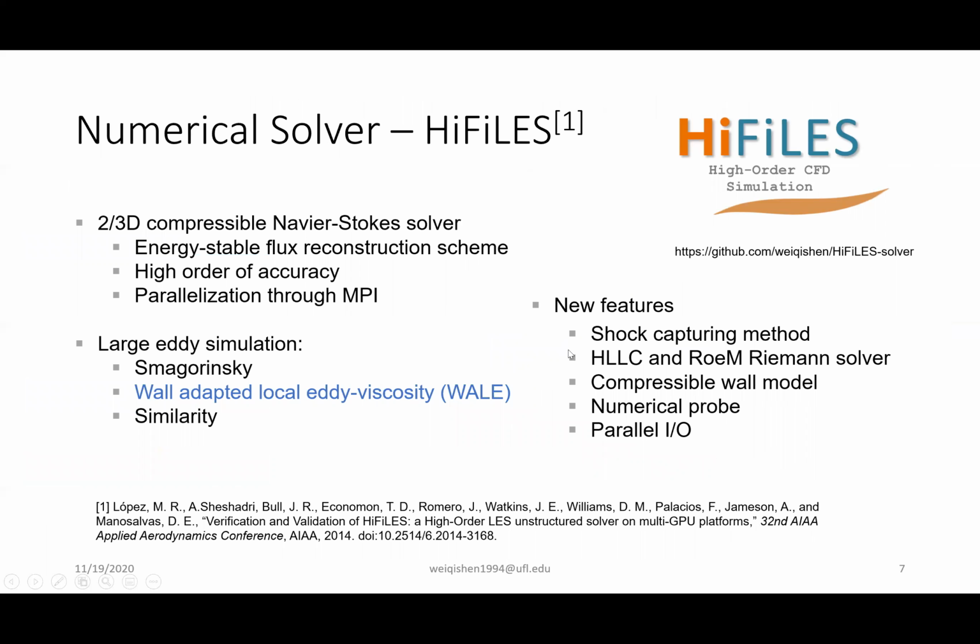The numerical code used in the present work is called HiFiLES, which was originally developed by Stanford University to demonstrate their newly developed scheme. The solver is a three-dimensional compressible Navier-Stokes solver, which is based on the energy-stable flux reconstruction scheme to achieve high order of accuracy on hybrid unstructured mesh. It can also be parallelized using MPI on distributed memory systems.